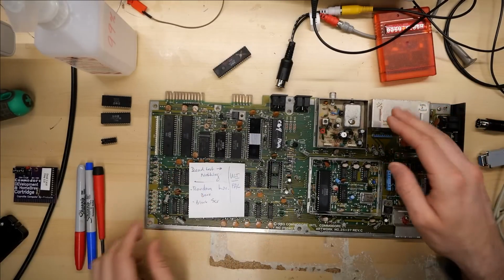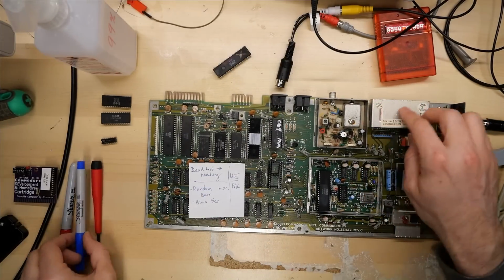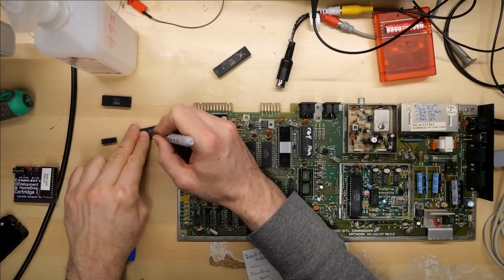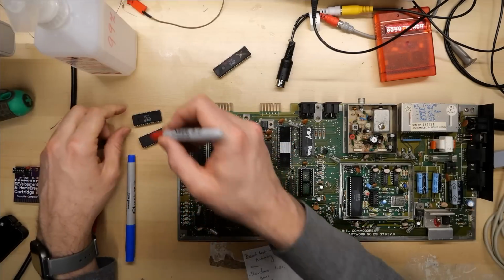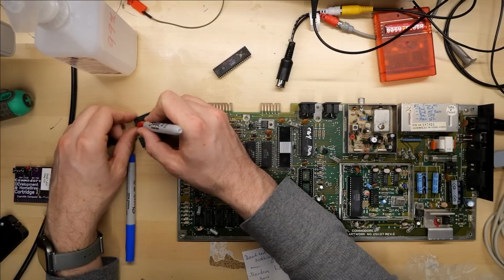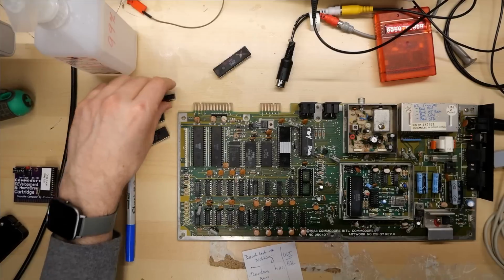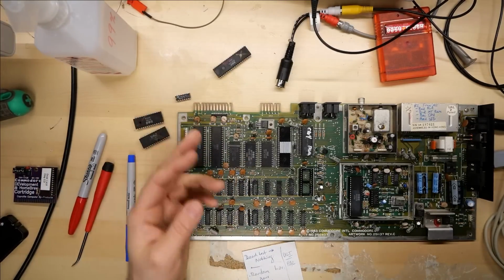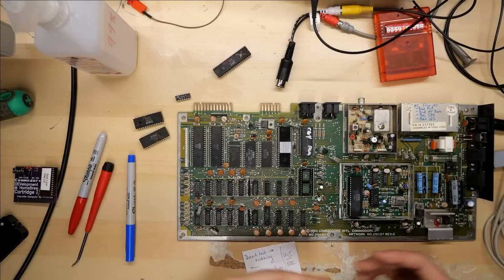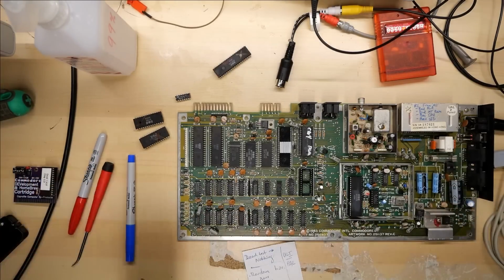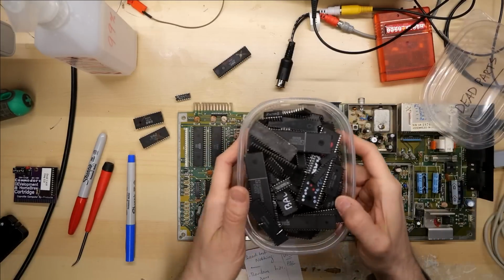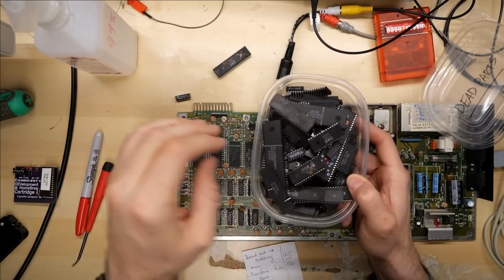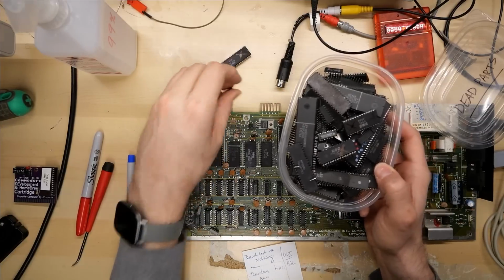But it is fixed now, so let me update the notes on the little cartridge shield here. I'm going to mark an X on the PLA chip. That is definitely bad. The X here on the SID, I'll just reinforce that. And this RAM chip here is one of the ones I had in my stock that was bad. So I think there were 2 of those that were bad as well. So yeah, bad chips galore. And dead part spin is here. So that's one bad SID. That's one bad PLA. Bad RAM chip.